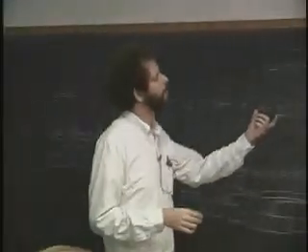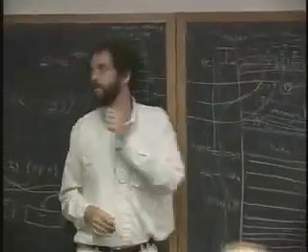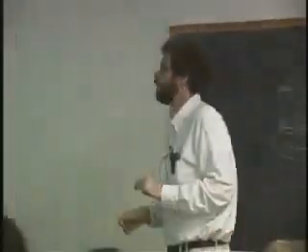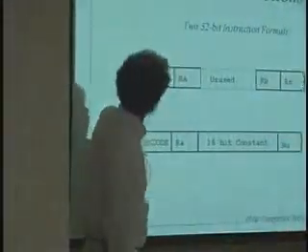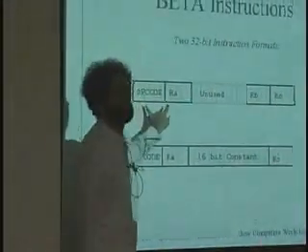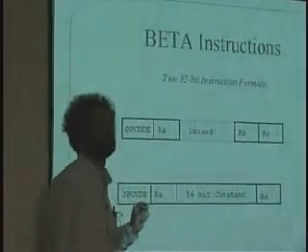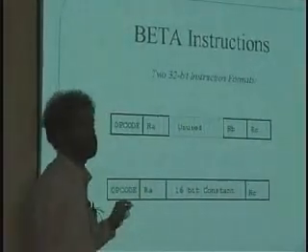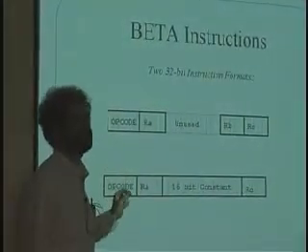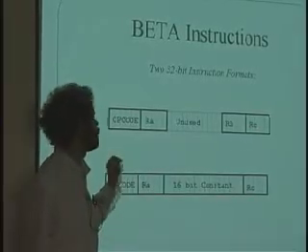Let's actually talk about the encoding of the instructions in the 32 bits. In general, we have 32 bits to deal with, and here's how we're going to do it. We're going to use 6 bits to specify what operation I want to do: plus, minus, times, things like that. With 6 bits, how many different opcodes can I have? 64. 2 to the 6 is 64.